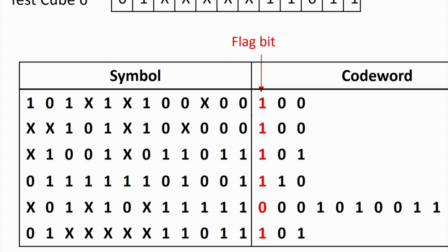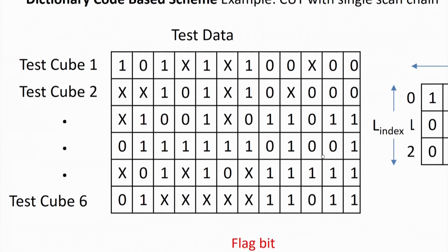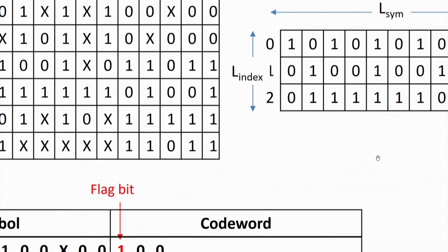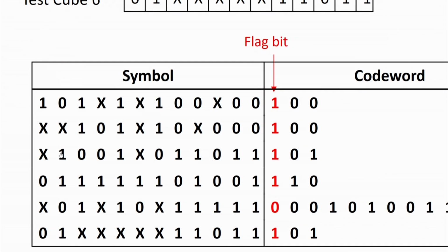So if I give the input 0 0, you have to generate the compatible test vector to this. Compatible here will be 1 0 1 0 1, x can be anything, 1 1 0 0, and this 0 will come over as 0 0 and 0. Basically, if you look at it, this is the first test vector available over here, the compatible version. Now you can find out that the third one will be compatible with the sixth.